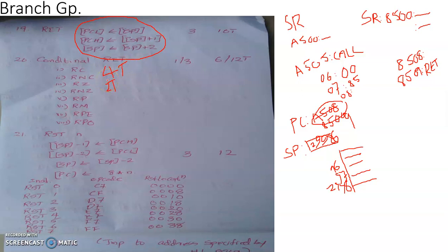Immediately after fetching and decoding in the 4th T state, it will identify that it's a conditional return instruction, so it has to check whether the condition is satisfied. Then it will check the content of the relevant status flag, and this consumes a total of 2 consecutive T states. So the opcode fetch part of this instruction requires 6 consecutive T states.